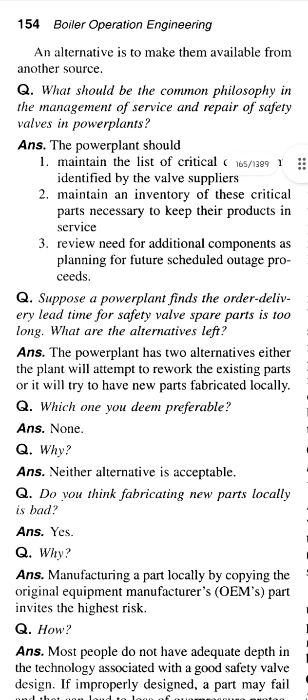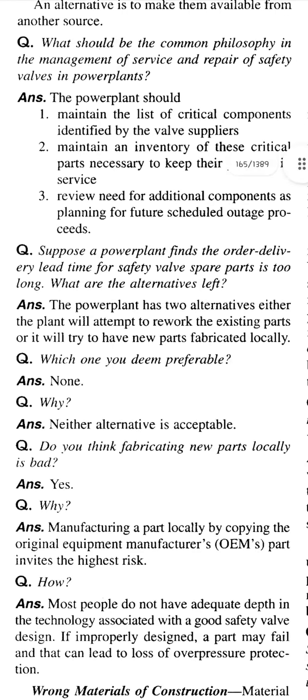Question: what should be the common philosophy in the management of service and repair of safety valves in power plants? Answer: the power plant should maintain the list of critical components identified by the valve suppliers, maintain an inventory of these critical parts necessary to keep their products in service, and review the need for additional components as planning for future scheduled outages proceeds.